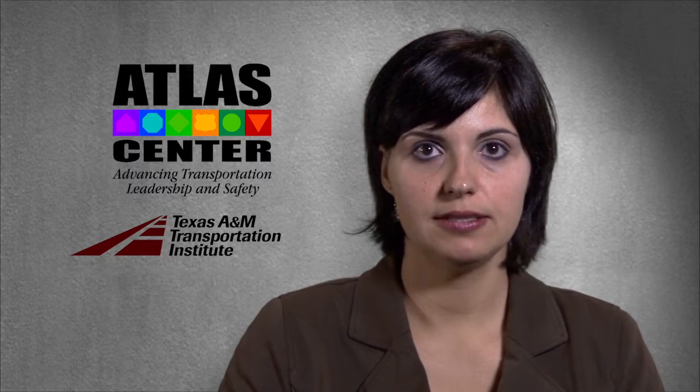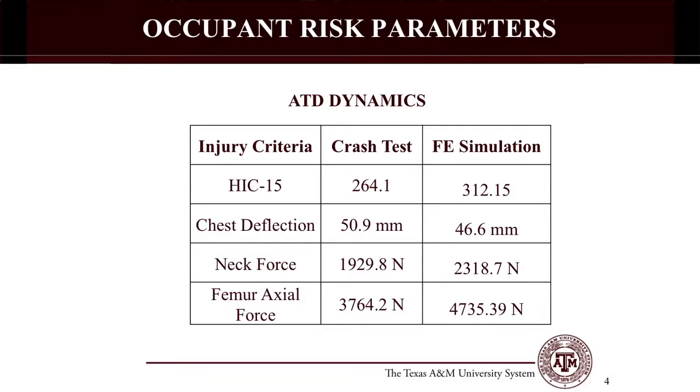The OIV was clearly above the prescribed MASH limit of 40 feet per second. This translates to a high risk of occupant injury. However, when the ATD HIC, chest deflection, neck, and femoral forces were evaluated, they were all well below the IARVs. MASH values suggest a failure of the test with respect to occupant risk.